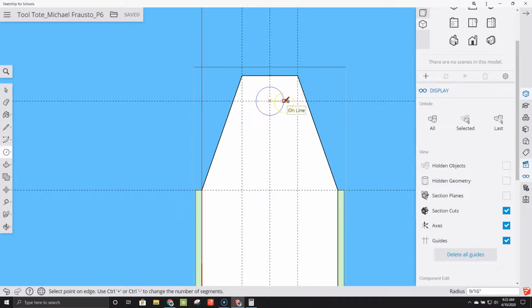Okay, here's a little bit of geometry terms. On the right hand side, you'll see that as I'm opening up this circle, it's reading in radius. Radius is a geometry term. It describes the length of a circle from the center to the edges. When we drill a hole, it's the length all the way through, so it's 2 radiuses. So 3/4 you would have to divide in half to get 3/8. So we just have to type in 3 divided by 8. 3/8 radius will create a 3/4 hole.